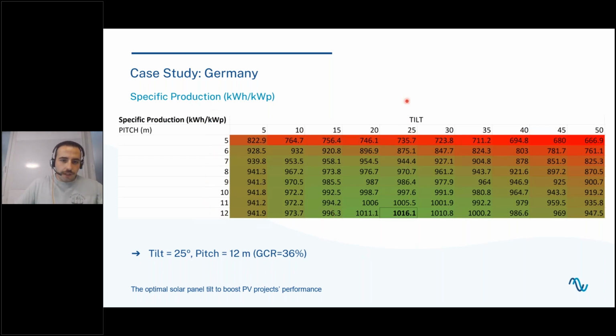In this case, it's also taking the tilt of 25, because it's a good tilt to avoid shading between structures. If we keep going beyond 25, we can see that the efficiency starts to decrease as we start having shadings between structures. Okay, it will be interesting also to generate other plots, not only taking into account the energy, but also the near shading losses or other kinds of losses to check it better.